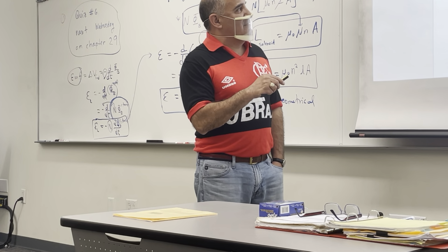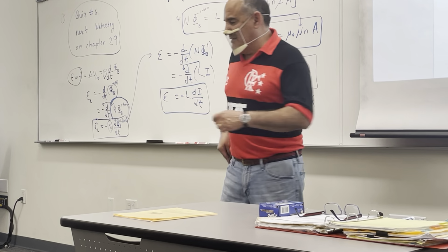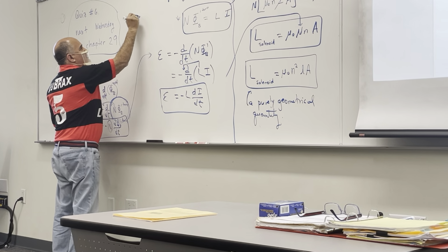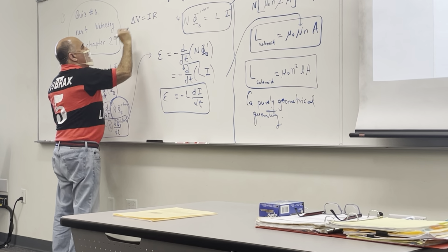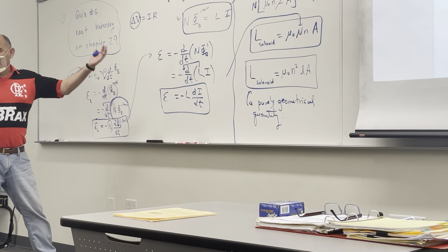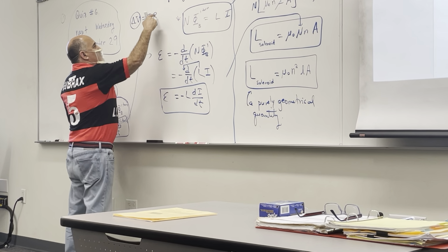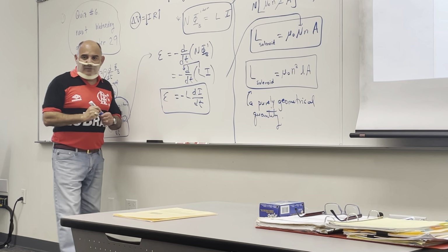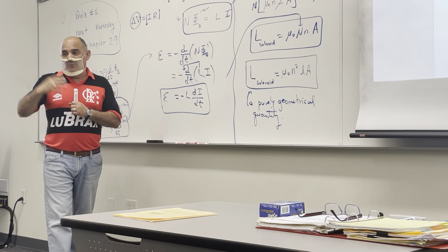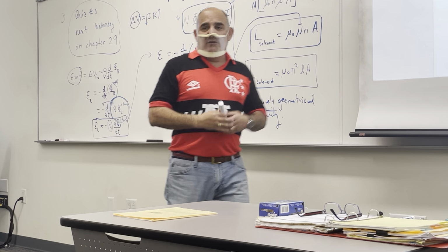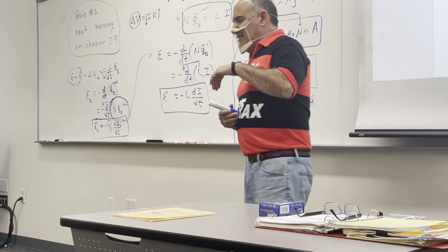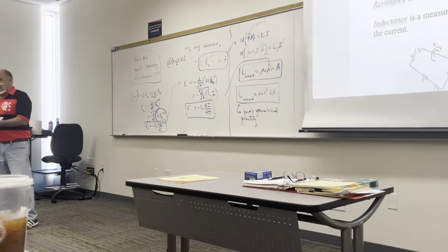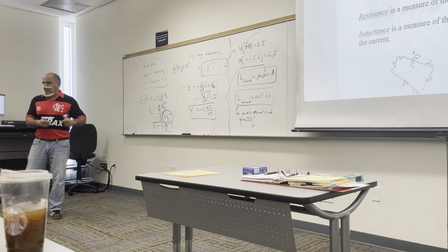If you think of resistance, and you think in terms of Ohm's law, V equals I times R. For a given potential difference across some wire or unit, the greater the resistance in that unit, the less the current through it. It makes sense. If there's more resistance, you're going to get less charges flowing, so the current is going to be less. So you can think of resistance as a measure of the opposition to current. The greater the resistance, the less the current for a given voltage.